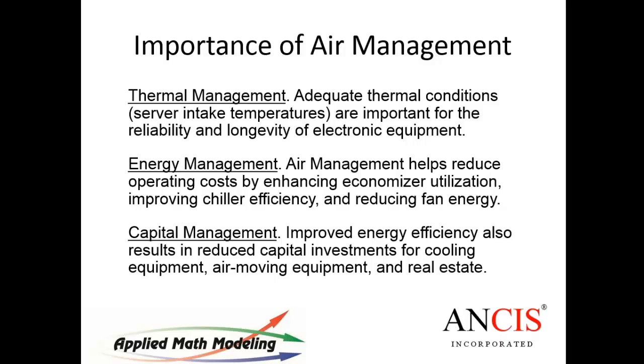The second is energy management. Like I mentioned, if you're supplying too much cool air to your space, you're kind of killing the efficiency of your cooling system. And the last one is capital management. If you do arrange your air management, you will notice that you can increase the capacity of your already installed cooling system, and especially your rack floor.